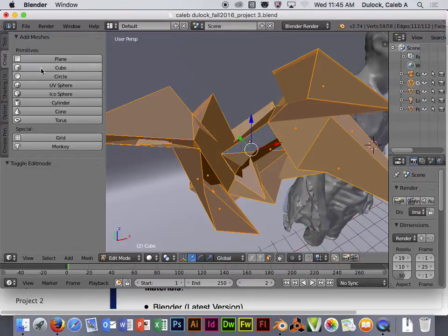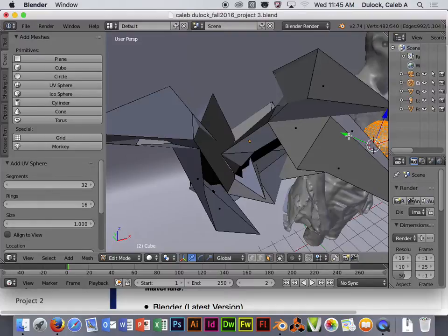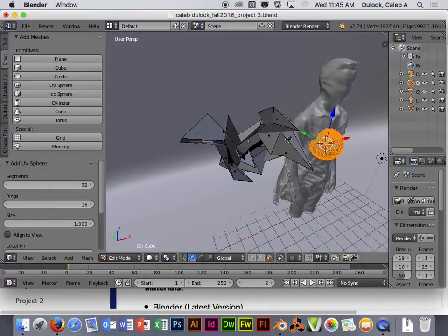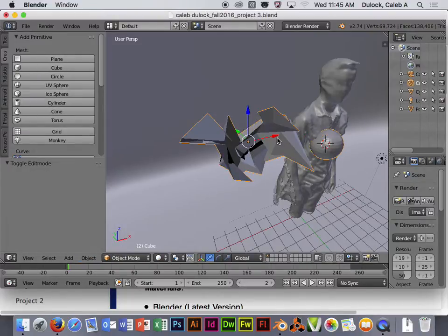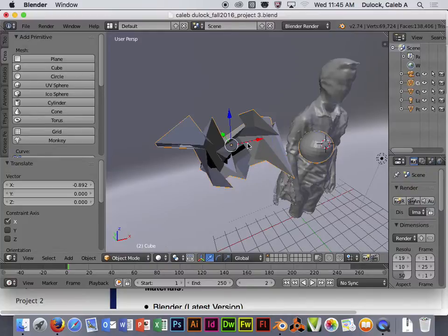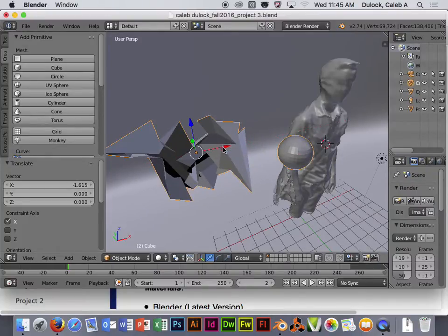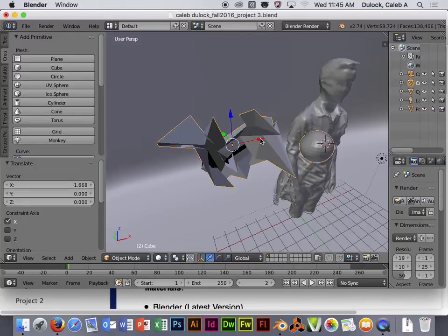If I add or create new shapes, if I use like the Create tab while I'm in edit mode, and let's say I add like a sphere, that sphere, technically in your design, is now a part of, or grouped with, whatever element you were just editing already. So this crazy polygon structure that I have on screen that's all sorts of funky abstraction, my sphere that I just added is now a part of that same layer too. So if I exit edit mode, both of those objects stay selected at the same time no matter what, because they're both joined in the same group together.